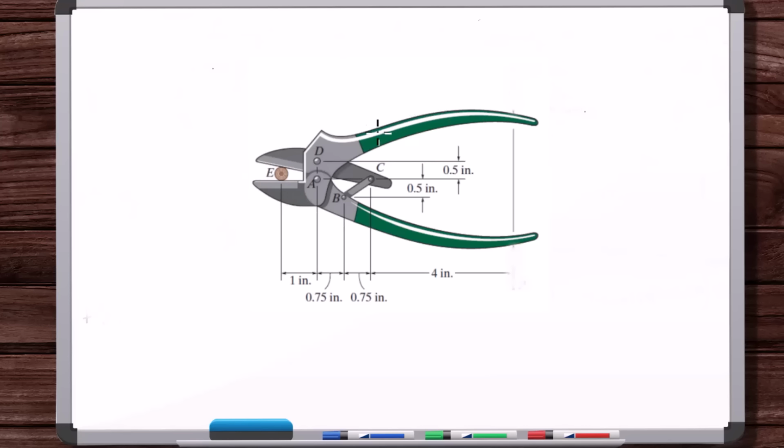Now we look at all the exposed surfaces. So these are all exposed surfaces. Where on these exposed surfaces was there contact? Whenever it was in its environment, at the snapshot picture, where was there contact with the environment? Well, here, between the hands. So we put those two forces there, okay? Now there's a lot more exposed surface, right? There's all kinds of exposed surface. Was there contact with the environment in any of these exposed surfaces? Yes, the air, but air forces are negligible here. It's not a hurricane or anything.